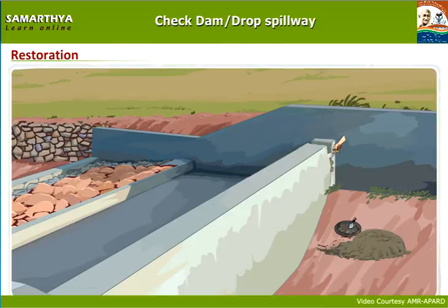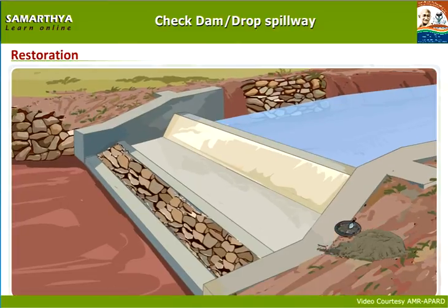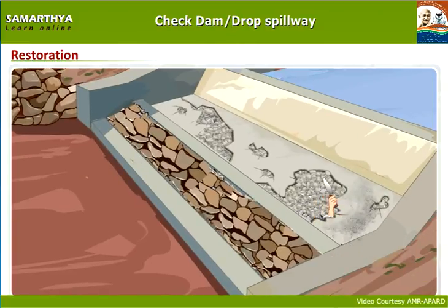In case there are heavy leakages or cracks, repairing must be taken up on the main wall or body wall. Repairing process must also be taken up if there are any leakages on both sides of the wall of surplus weir. If the concrete apron is damaged or cracks are developed, remove the portion and clean it with water.